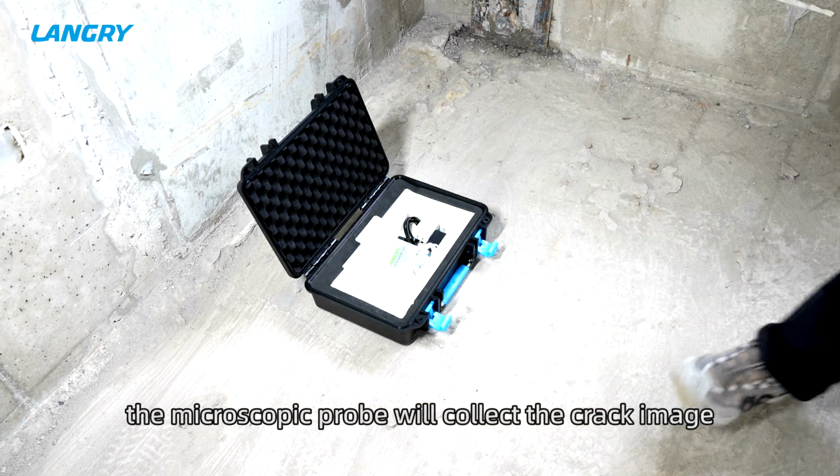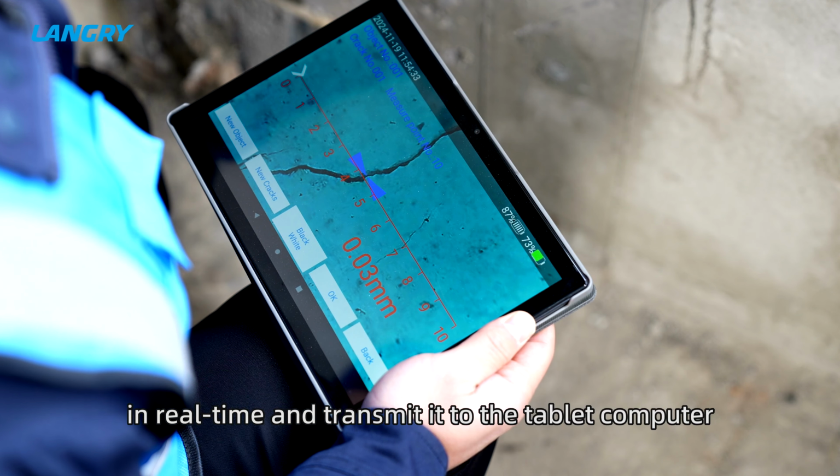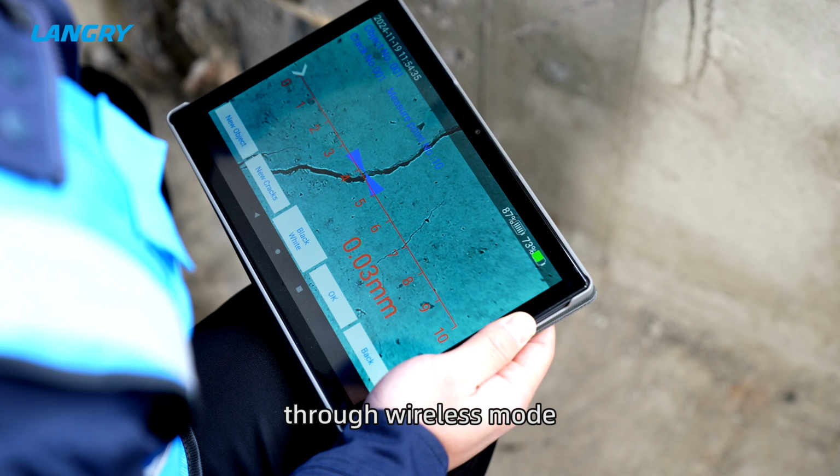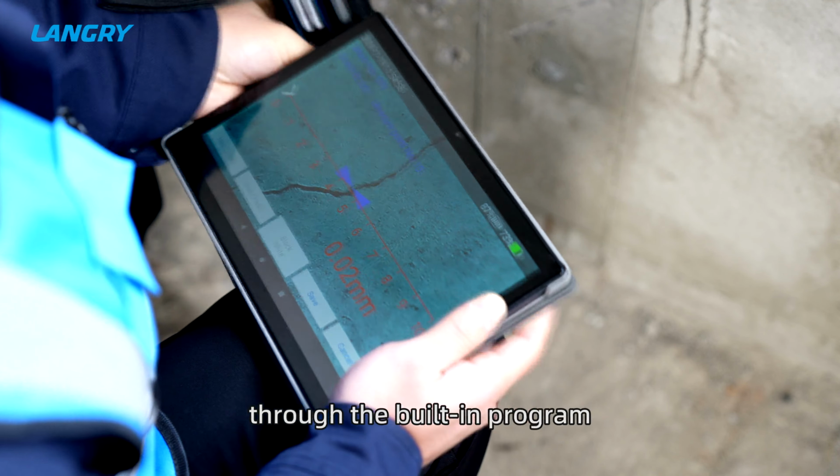During measurement, the microscopic probe will collect the crack image in real time and transmit it to the tablet computer through wireless mode. The tablet computer will display the received crack image in real time and automatically capture the crack and display the crack width value through the built-in program.